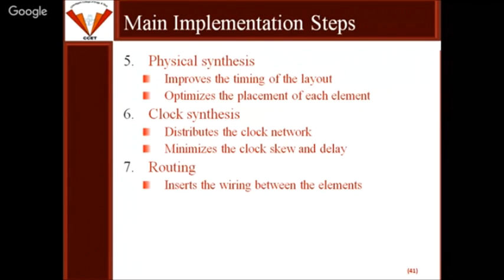Similarly, the power distribution, because as the interconnect length is increasing, obviously through the interconnect there is power, or you can say heat dissipation. We require some amplifiers in the middle so that the same logic level should reach the different blocks. For blocks which are farther away, when the signal of 1 or VDD reaches that point, it may not be VDD, it may be less than that. So we have to adopt some techniques so that the same power will be distributed to the different elements.